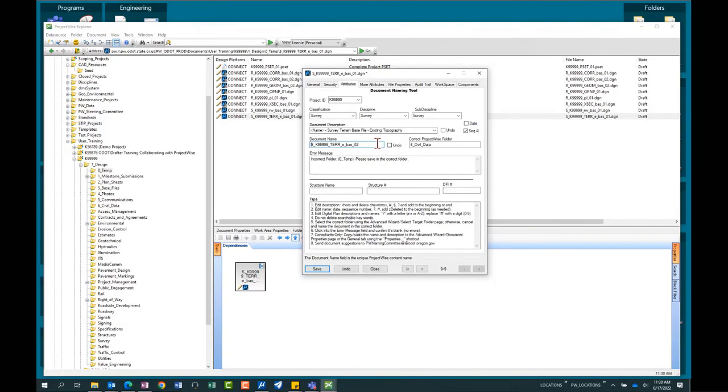The reason I'm so particular about those .dgns at the end is because of Print Organizer. I'm going to get there. Print Organizer records the document name. If we don't put the .dgn at the end, it means the print set is no longer portable. And if you had your server migrated like we did last week, your print set will probably not work and you'll need to recreate it. So we're going to make this rock solid.